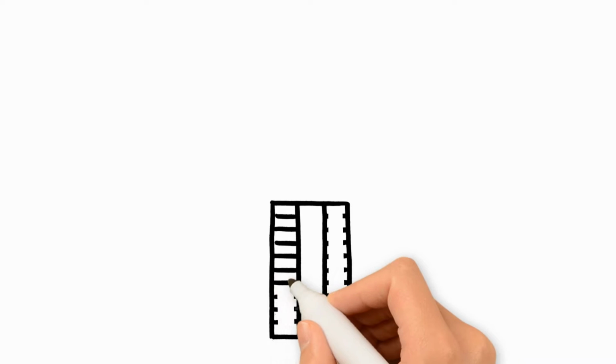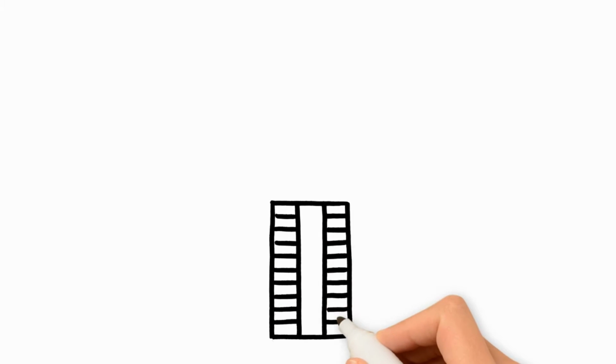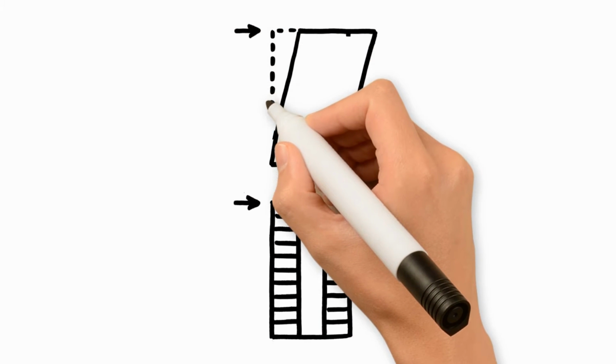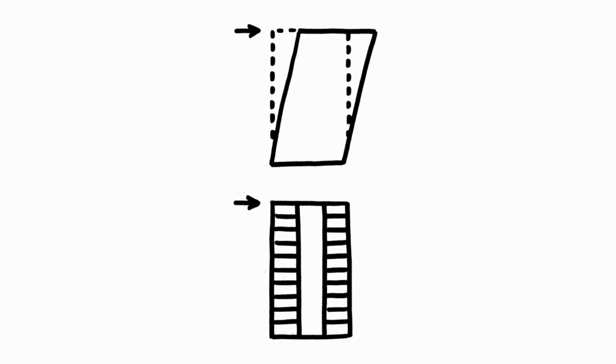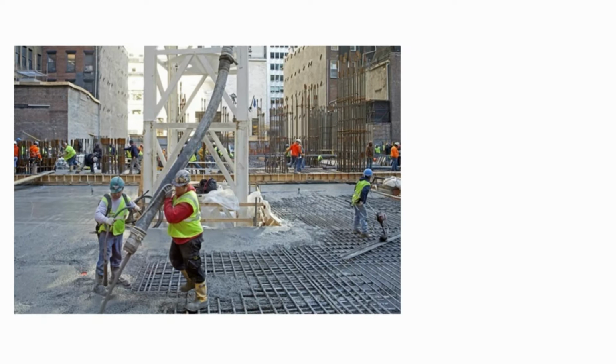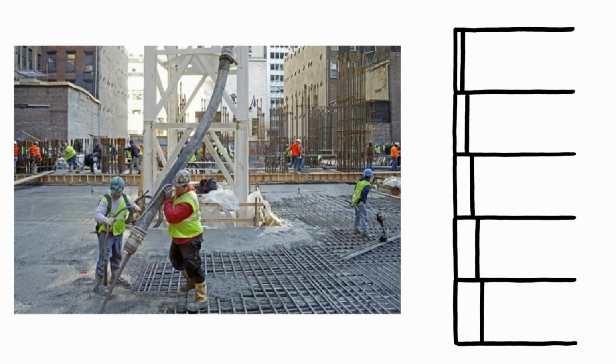This allows the central tube to be much smaller. However, the external facade consists of a series of rectangles. When a rectangular frame is pushed from the side, it deforms. This effect, known as racking, is resisted by the reinforced concrete connections between the beams and the columns that prevent rotation. To provide more stiffness, the frame is connected to the core using floor slabs which transfer loads between the two.